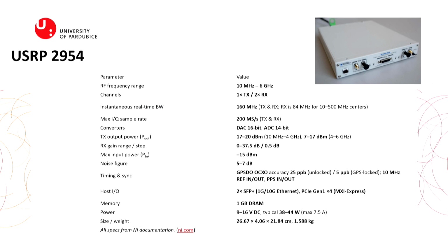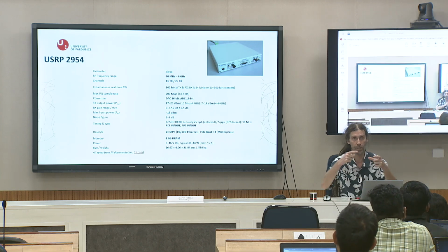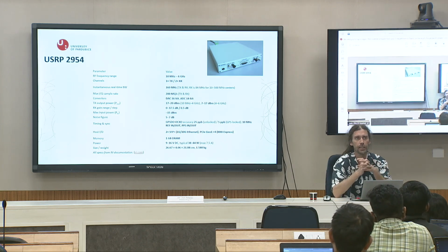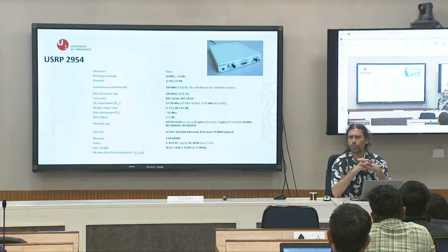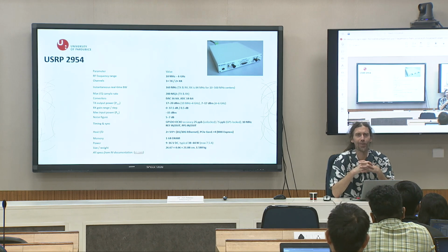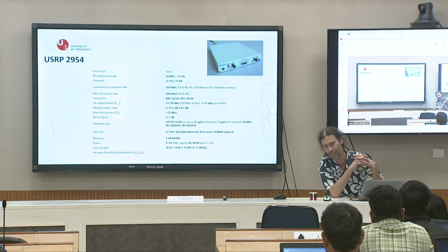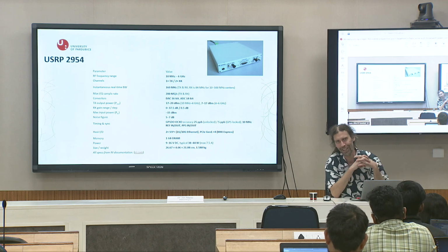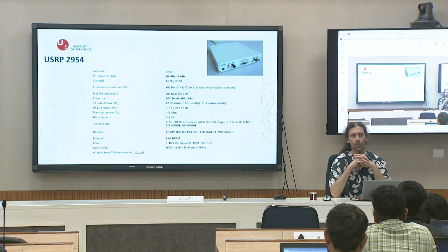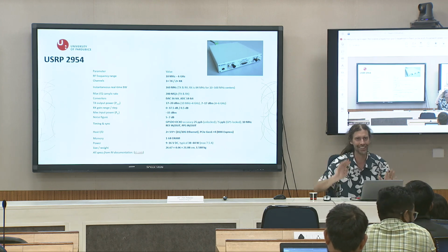Okay, frequency range from 10 MHz to 6 GHz. It is very impressive. It is a very, very high range, and because of this, the price is of course a little increased. This ADALM-Pluto that I mentioned, the small blue one, is up to 3 GHz. Okay, officially it's up to 1.7. No, it can be software unlocked to higher frequency where it's not officially supported, but works. Of course, on your own responsibility. It was not advice.